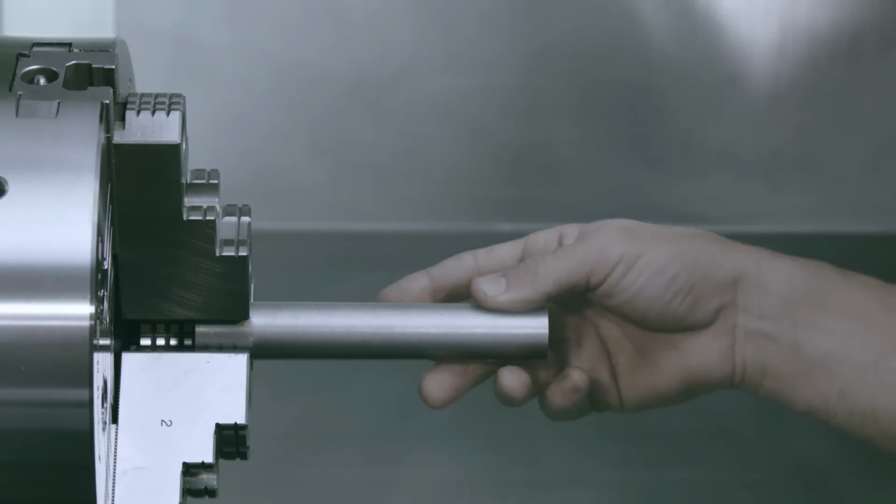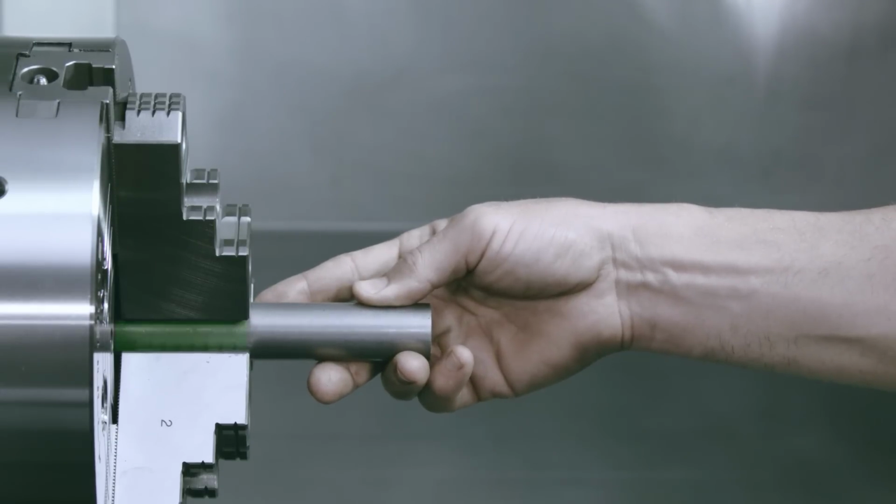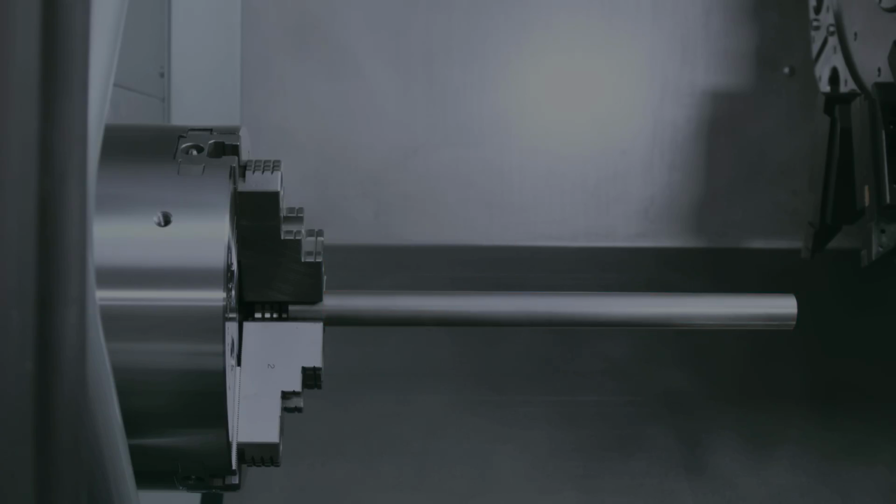However, the same 6:1 part, clamped with only 3 inches hanging out, will probably not need tailstock support, because now the unsupported region is only at a 3:1 ratio. Once you've exceeded an L to D ratio of 10:1, parts become so flexible that even tailstock support may not be enough. So, to summarize, we recommend when unsupported L to D equals 3:1 or less, tailstock support is probably